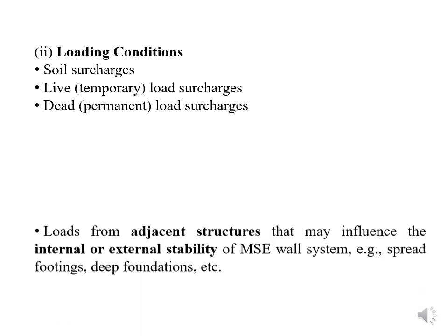The other points you have to keep in your mind: loading conditions, soil surcharge, live load surcharge on the embankments, right? So all the points, dead load surcharges also you have to keep in your mind before starting the design.